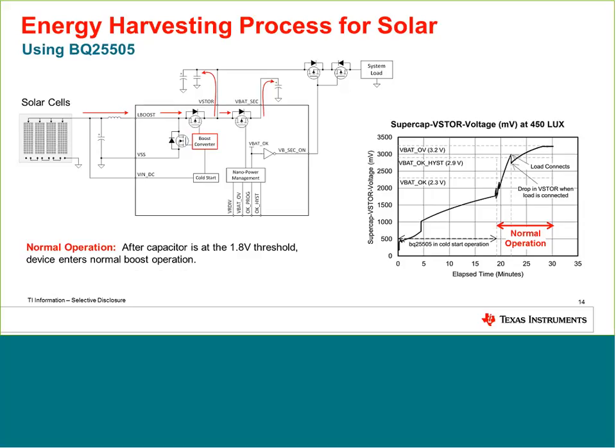We'll take a low voltage from the solar cell, boost it, and charge the main storage capacitor, and also charge a secondary storage capacitor bank. So that voltage will keep rising, and at one point when it arrives at 3.2 volts, it will switch to the next level and will turn on the load.